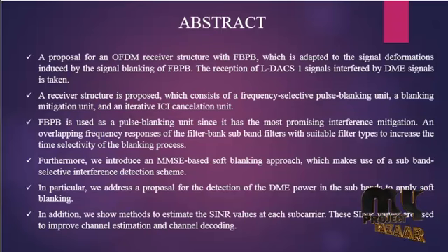LDACS is an existing system. It causes interferences, so we are going for the FPBB. A receiver structure is proposed which consists of a frequency selective pulse blanking unit, a blanking mitigation unit, and an iterative ICA cancellation unit.